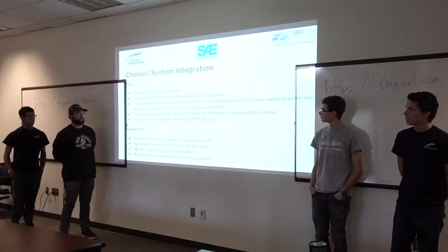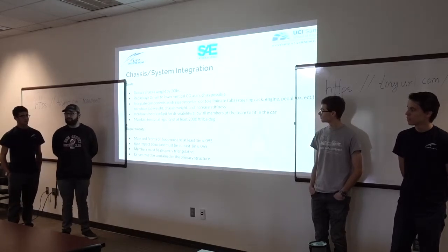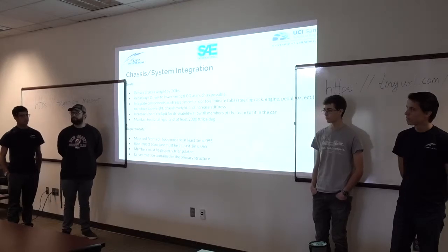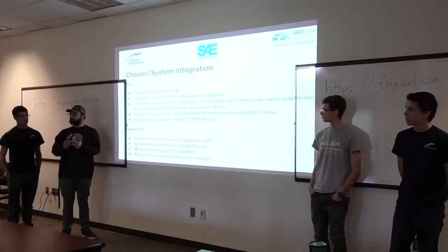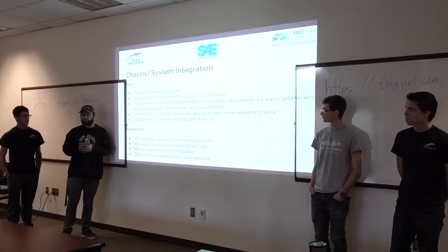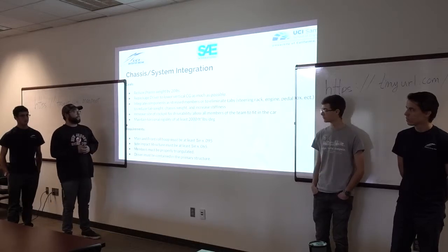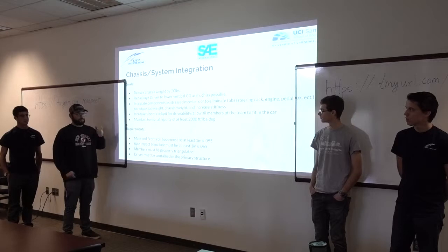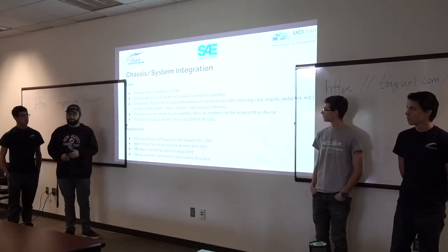Repackage the driver to lowest vertical CG. The driver is at about a 42-degree angle backwards, similar to F1 driving angle. Integrate components that stress members, such as the steering rack and the engine.